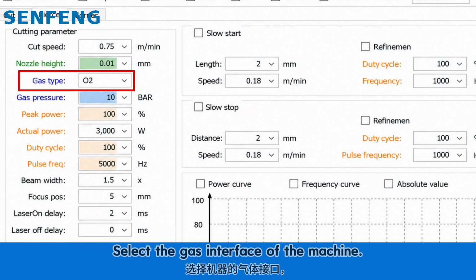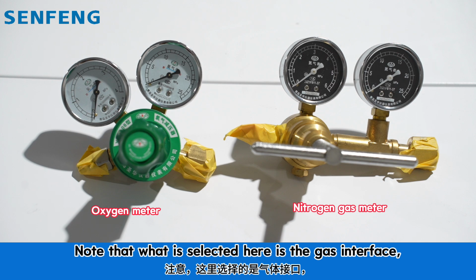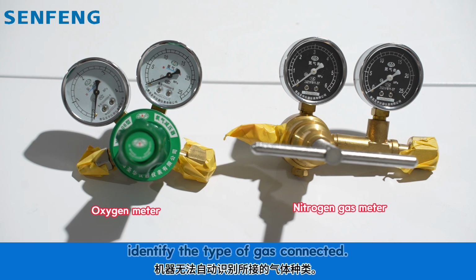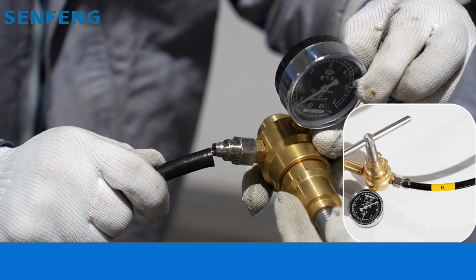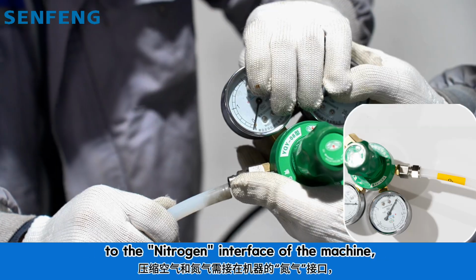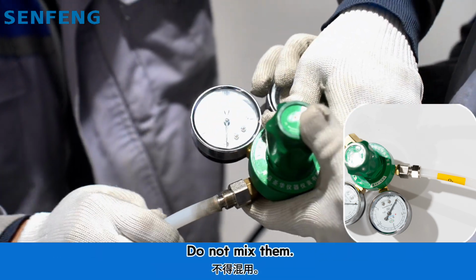Gas type. Select the gas interface of the machine. Note that what is selected here is the gas interface, and the machine cannot automatically identify the type of gas connected. Compressed air and nitrogen should be connected to the nitrogen interface of the machine, and oxygen must be connected to the oxygen interface. Do not mix them.